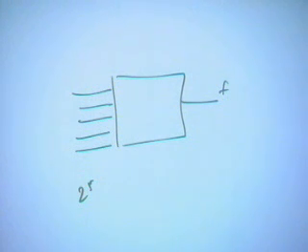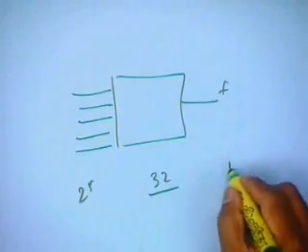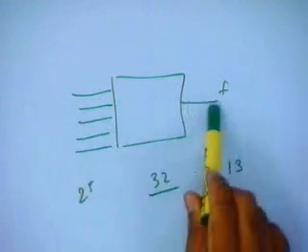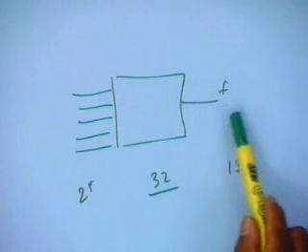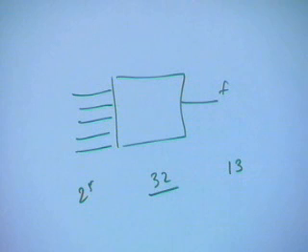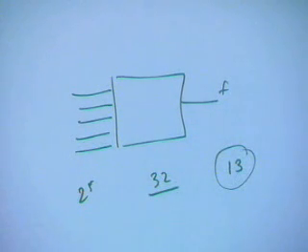If you consider the function, out of, let us say 32 min terms, let us say this function's output is 1 for 13 of them. So, you apply all these inputs and count and see whether there are 13 ones or not. So, you of course will require a counter to consolidate the result. The way you are taking the result and generating it is you are essentially putting it into a counter and counting. And once you compare, if you get 13, then of course you can say that the circuit is functioning correctly.